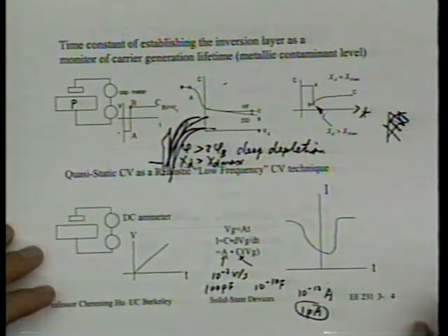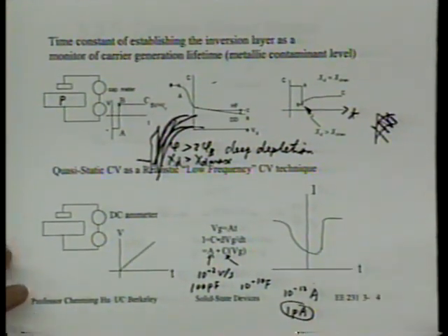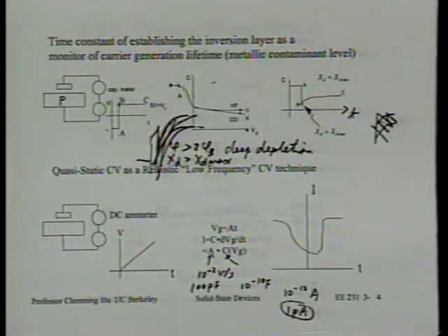A variation of this, I would not go into detail. I don't know too much detail about that either. There's one company that sells one equipment that allows you to essentially do this kind of CV technique measurement, basically measurement of the capacitance, without actually putting down an electrode. If you just have a semiconductor, maybe with oxide or even without oxide, it allows you to measure CV.